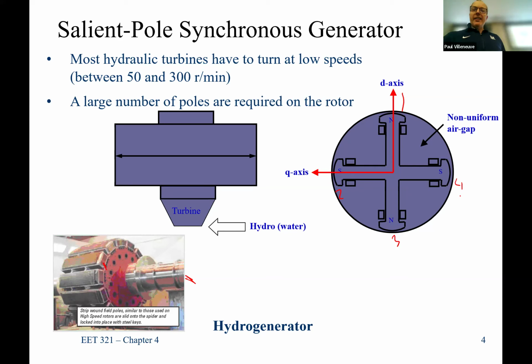So one thing, and this is if you really get into graduate stuff where you're trying to understand rotating fields and all that stuff, we live in a stationary world, but sometimes we want to go ahead and put our axes on a rotational aspect. So in this case, we have to generate a set of new axes that rotate along with the rotor. So this direct axis or D axis is lined up with the north. And then we have a Q axis.